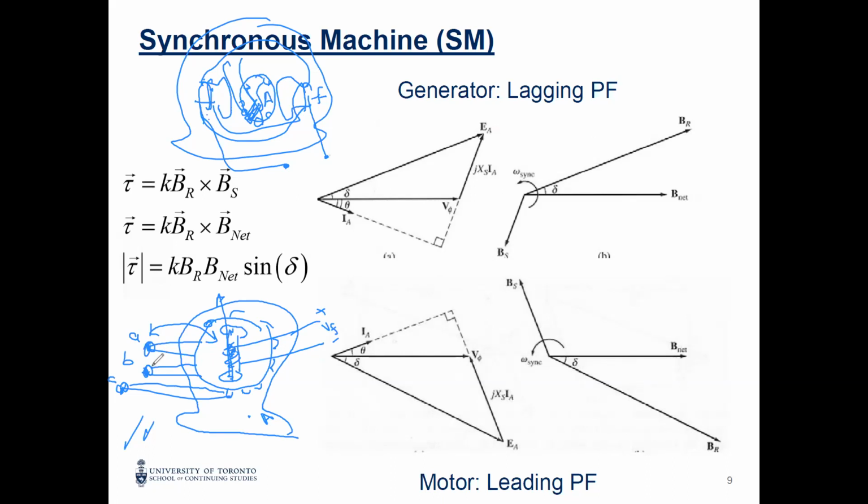Okay. So armature in the stator for the synchronous, field in the rotor. Do we need the DC source for the synchronous? Yes, always. How do we do it? As I said, this is called the field, or sometimes we call it the excitation. You can check online, because this is a very interesting part: what kind of excitation, and how can we provide the excitation of the synchronous machine by the DC source.